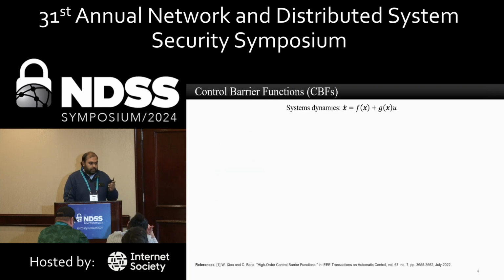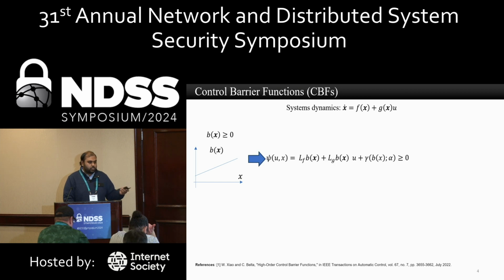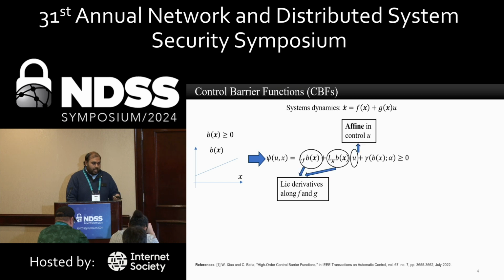I will very briefly introduce a specific type of function, which we call CBFs. These are the functions that we use to introduce the constraints, or the rules, in the control zone into our controller. The idea is that if you have these constraints, let's say the safety constraints, you can map them into another set of constraints such that the control input will appear. Control input meaning steering, acceleration, deceleration, and so on. And this has some specific properties, which I will also touch on briefly in the next slide.